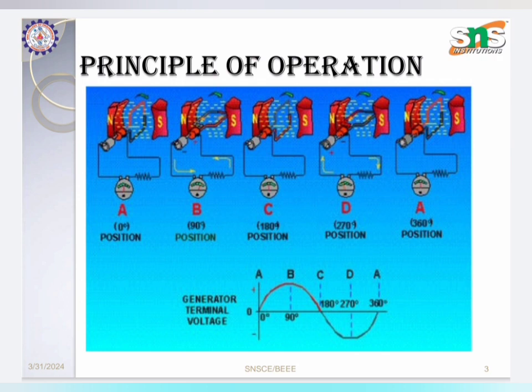Again at 180 degrees the lines are parallel to the conductors, and hence there is no flux cutting. So at 180 degrees the EMF is 0.